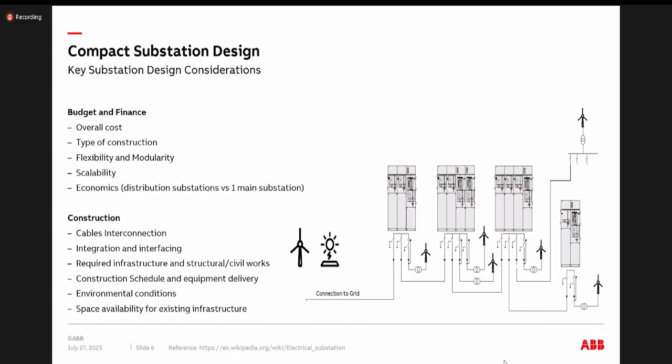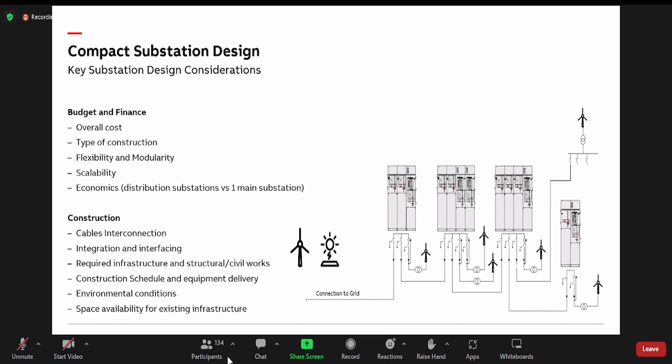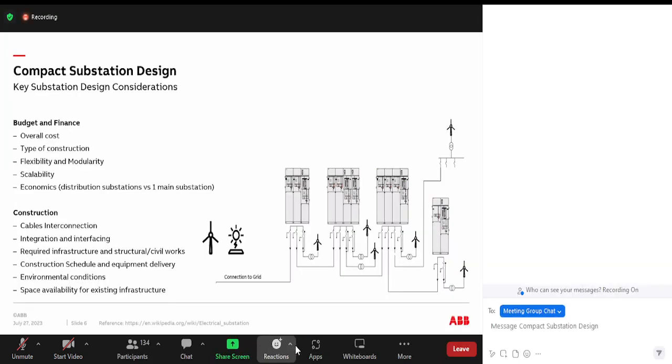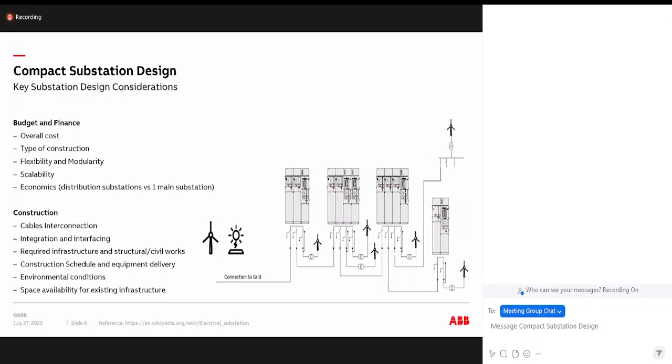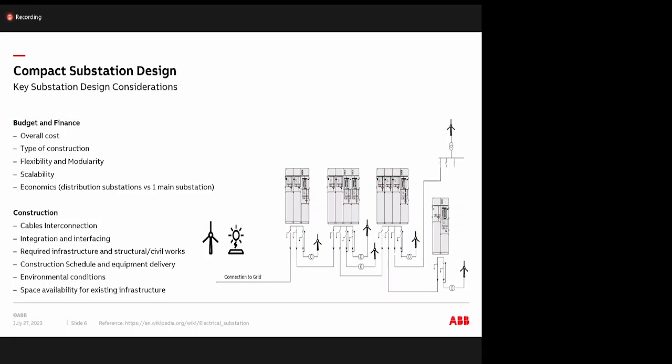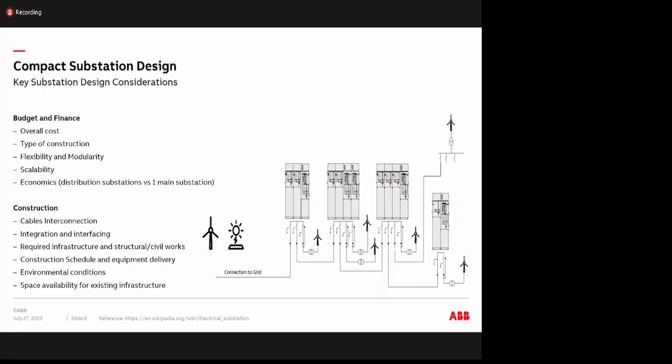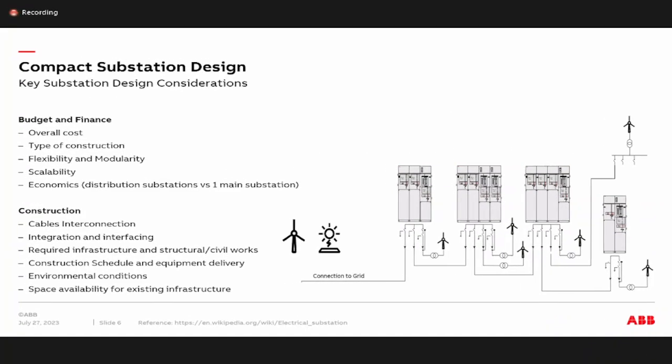Hindi ka pwedeng tumakbo doon sa area na yon dahil doon nga dadaan yung mga equipment, and then if you don't run the services, then that will actually delay the testing commissioning of the project, no? So we have to determine how we will be able to do the cable interconnection, of course, the integration and the interfacing of each equipment, and what would be the required infrastructure, yung mga structural works, mga civil works required, of course, yung coordination natin with regards to the foundation, the foot frame, the equipment framing, no? So we have to consider all those things also once we are doing the design.